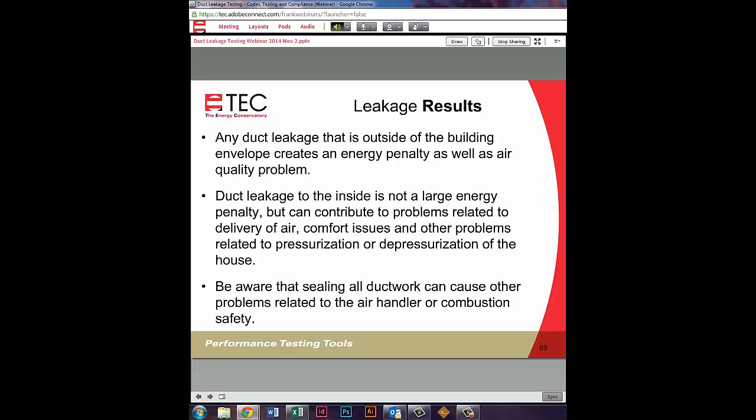So when the homeowner decided to turn on the air conditioner, there wasn't enough air to actually move through the system to make it work right. So the cooling coil of the air conditioner wound up freezing and creating an ice block in the air handler, and so there was no air going through.